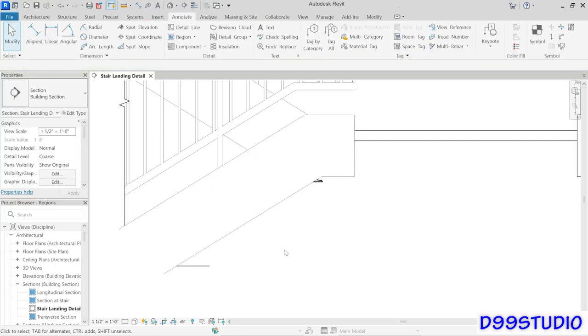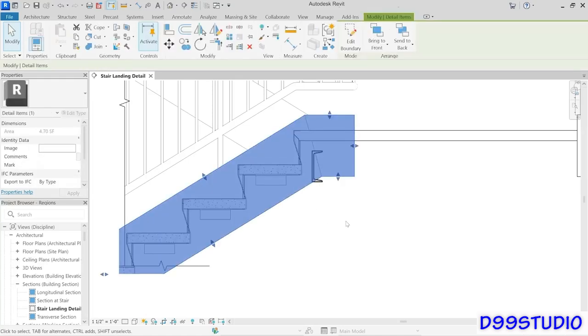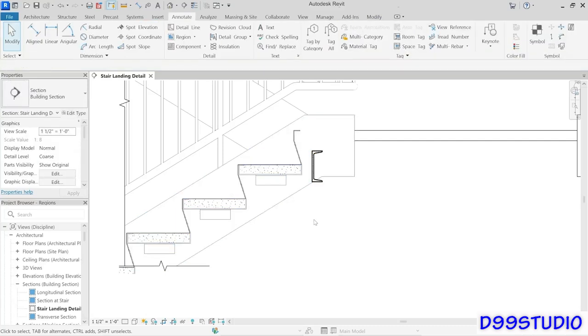But when we're done, it will look something like this, but you're probably thinking, well, that doesn't look so good. Well, the next concept that I want to talk about is stacking order. When you have these detail components in a view, you get to determine which one sits on top of the others. The easiest thing to do is select one of the elements, and then you've got the Arrange buttons here, and you can either bring them to front or send them to back. In this case, I want to take this masking element and send it all the way to the back. That's going to put it at the bottom of the pile. And notice that all of the other detail components will jump forward relative to it. And when I deselect it, it looks like that.